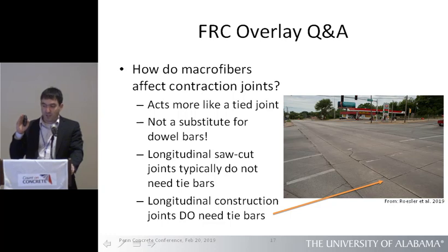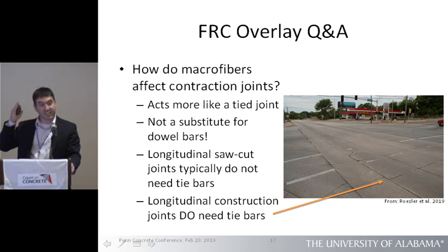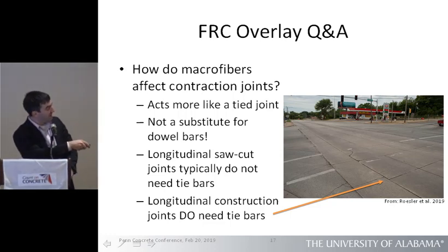Well, first of all, we're not saying that you remove dowel bars. If your design calls for dowel bars, you should keep your dowel bars in. The fibers are not going to act in the capacity to replace dowel bars. However, it could potentially reduce or eliminate tie bars. However, if it's a construction joint and not a saw cut joint, you still need tie bars for this very reason right here.